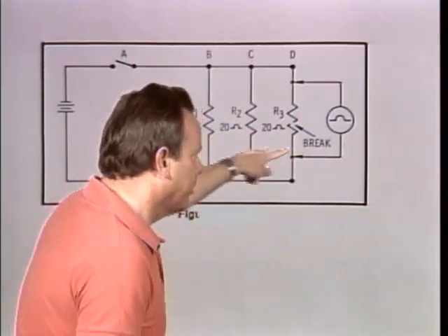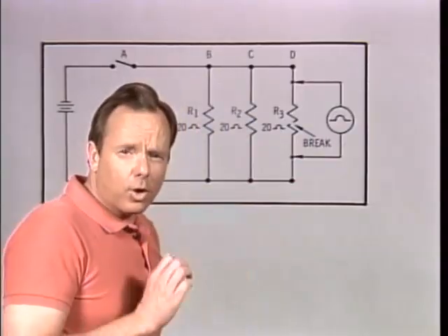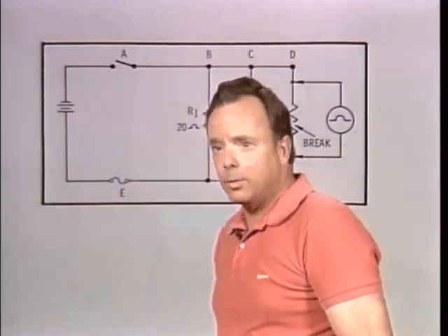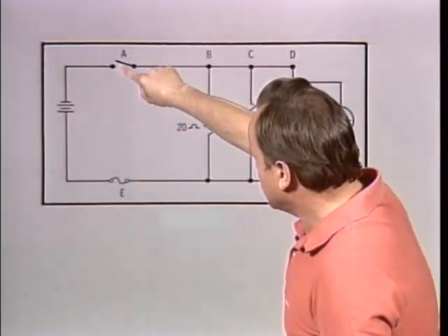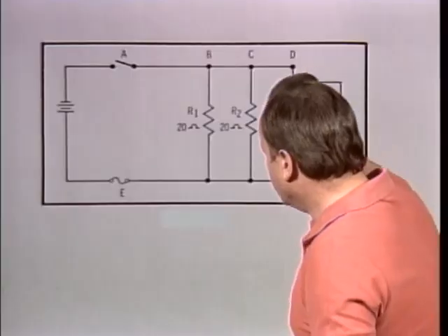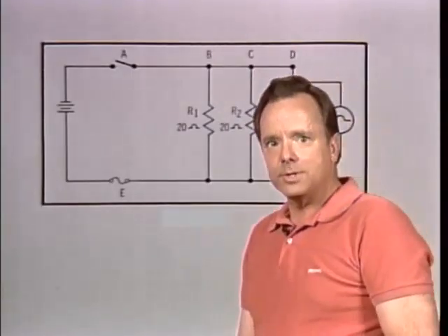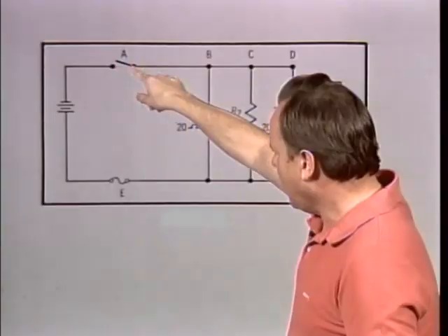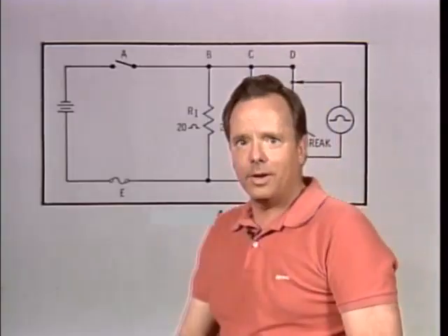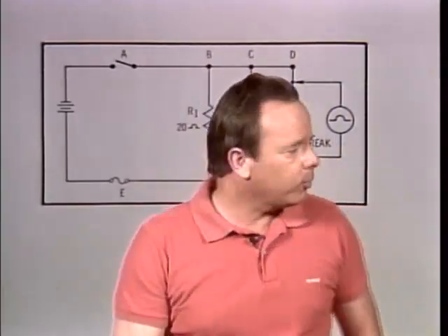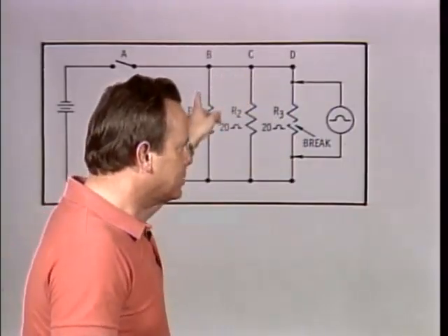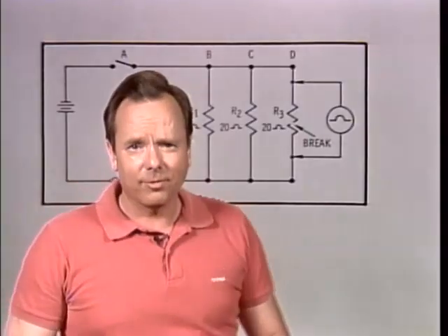And we're sending a current through these two resistors. In order to do that, you must have at least one end of the resistors disconnected. In this particular case, we have the switch open, and therefore we can send a current around. Then the ohm meter measures how the current goes and measures the resistance. Now, if you did not have an open circuit, you would have a voltage going through here and a current going through here, and that, of course, would mess up your reading. So the correct way to use an ohm meter is to put it parallel to the resistors you want to check and have at least one end of the circuit open, and that's what we have right there.